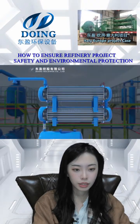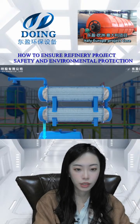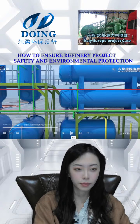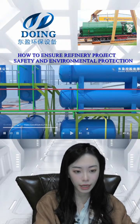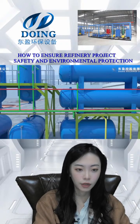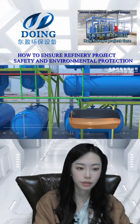And then there's a third cooling procedure, the horizontal condensers. We have two condensers, each with 37 pipes of 76 millimeter. It will greatly increase our cooling area and ensure that most of the gas is cooled after the first three cooling systems, and this cooled oil gas will be temporarily stored in this oil storage tank.